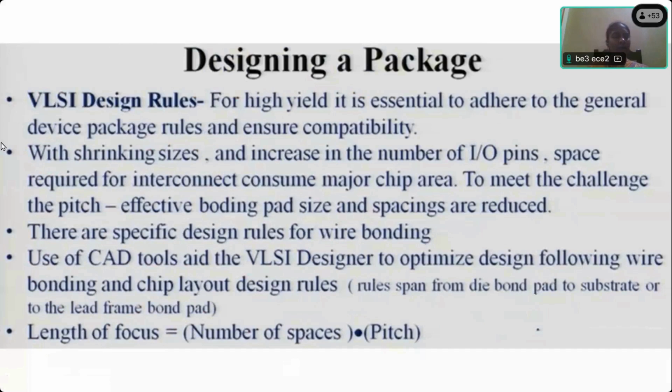So for that, there should be a proper matching with the schematic diagram drawn. You have done it in DSD, digital system design. You are doing Verilog coding. After that, you are dumping it in the FPGA kit. You are doing the coding, which is software level, then you are taking it into hardware. So that matching should take place. You are writing a test bench. With the minimum test vectors, the entire design should be checked, and it should say whether it is functioning properly or not. Then only it should be taken to hardware.